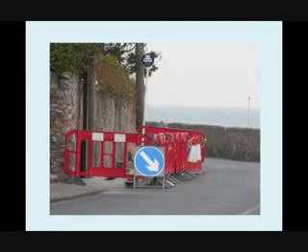This one in particular, as far as pedestrians is concerned, is a very bad example. We're on a very sharp bend here. The footpath is completely taken out. There's a bus stop here as well. It's not covered over, so it's quite apparent the bus company have not been consulted about the works either. If you were an elderly pedestrian coming down the footpath here and you had to negotiate these into live traffic on that bend, it could certainly be a very dangerous situation. So, again, a bad example there.